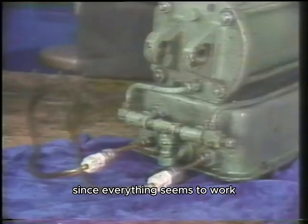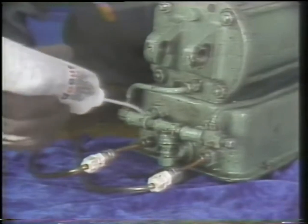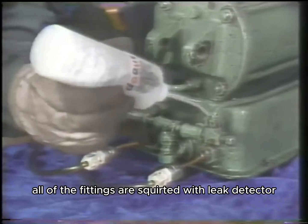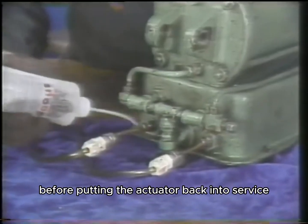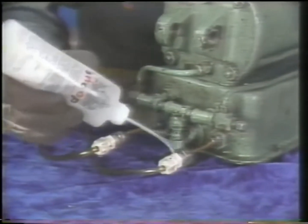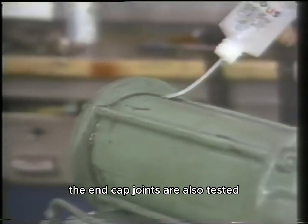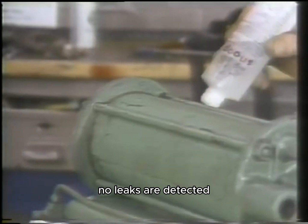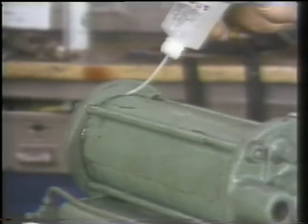Since everything seems to work, the only remaining task is to check for leaks. All of the fittings are squirted with leak detector. Any bubbles would indicate air leaks, which would have to be repaired before putting the actuator back into service. The end cap joints are also tested. No leaks are detected, so this actuator is ready to go back in place.